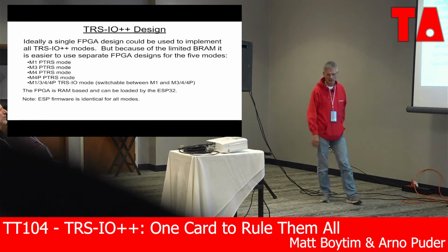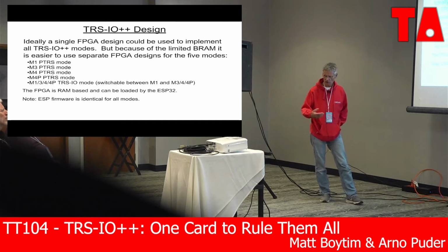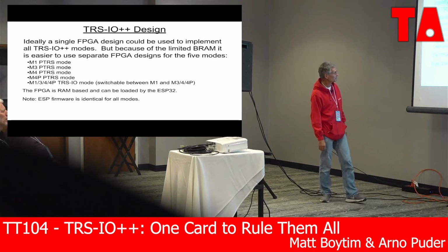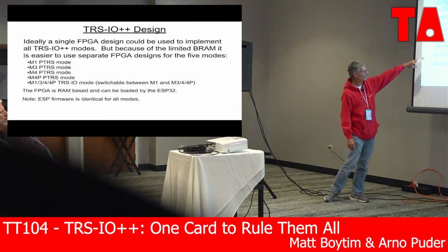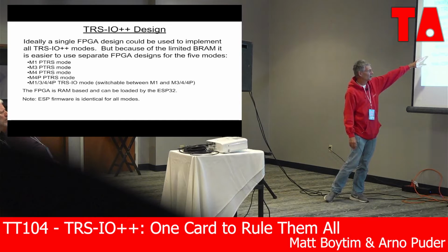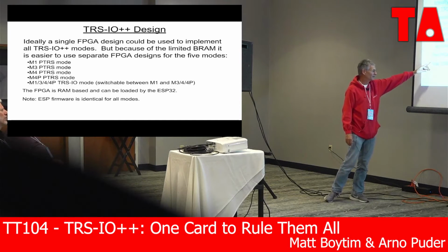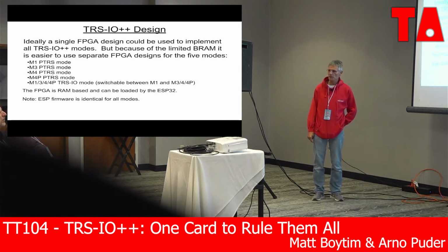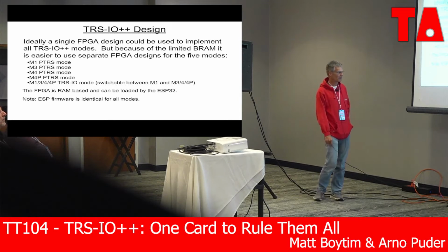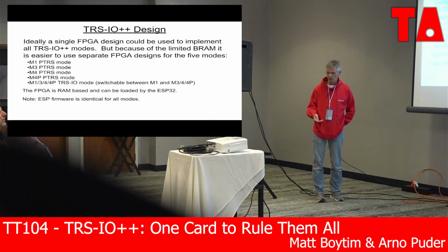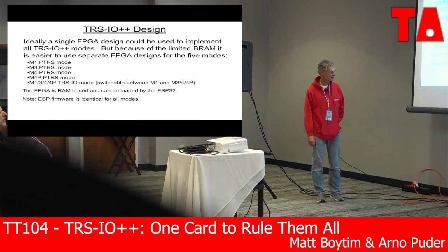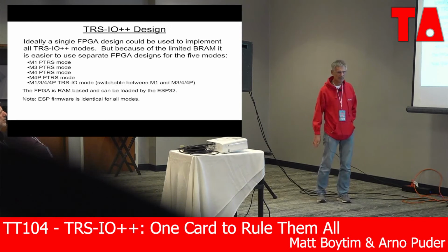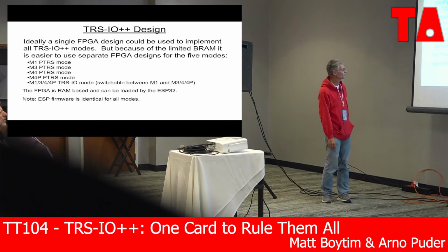And so that's where the loading of the program comes in. With the ESP able to load the FPGA program, it's not so terribly clumsy. You don't have to get your programmer out and do it. You just select the mode with the dip switches, it loads it up, and boom, you're up and running. So as I said, it can load the FPGA firmware. And another note is the ESP firmware is the same for all modes. That would be inconvenient to program because that takes several minutes. It's in Flash. So we run one ESP firmware and 5 FPGA firmwares.